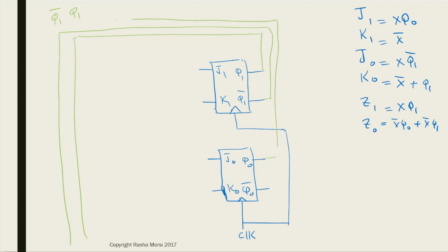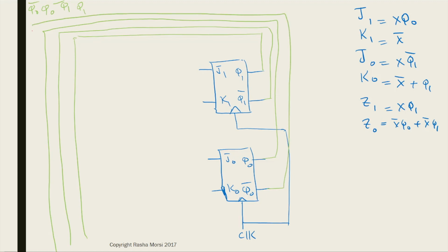So then you have your input lines right in front of the circuit. I'm just going to redraw those a little bit higher up so that we can have our space. And now we need the X input because we have one external input. So we're going to draw that right there and give it an inverter because in some cases we have an X bar that we need.